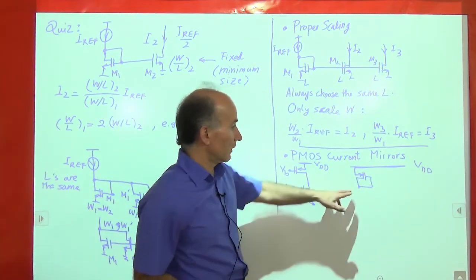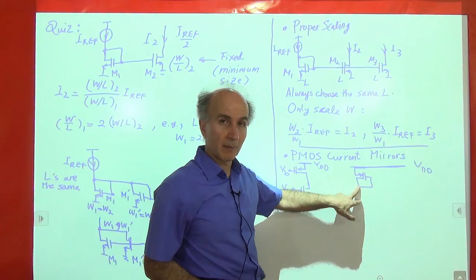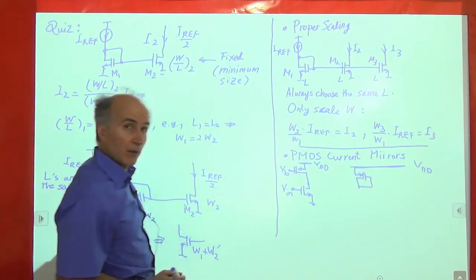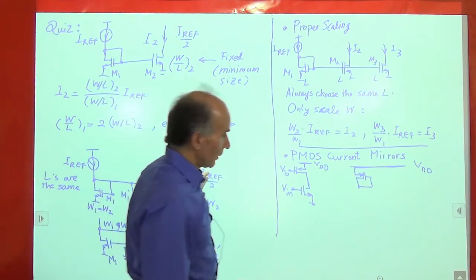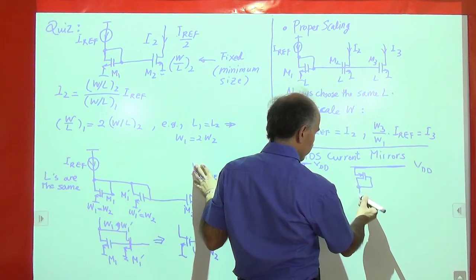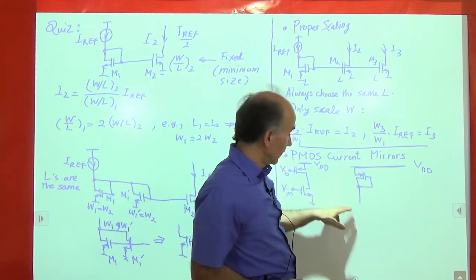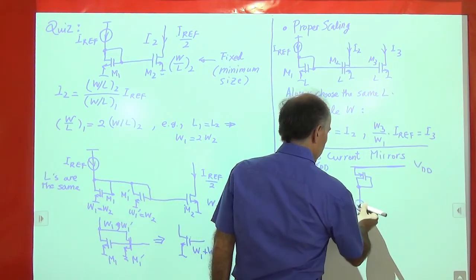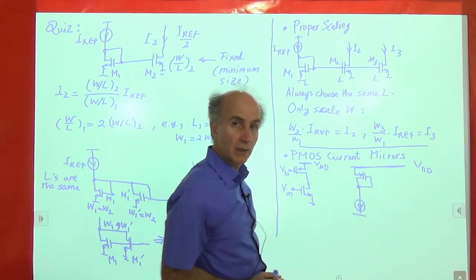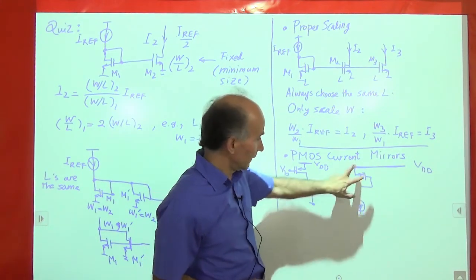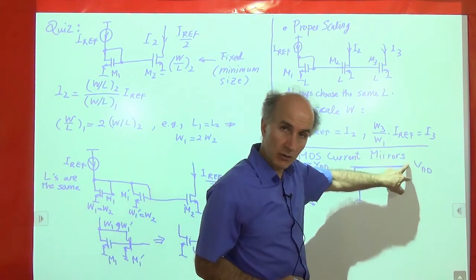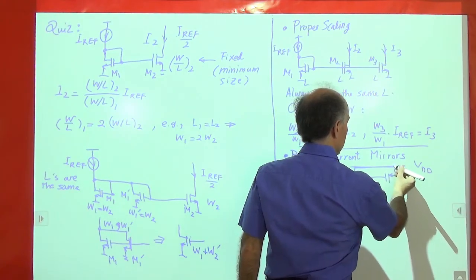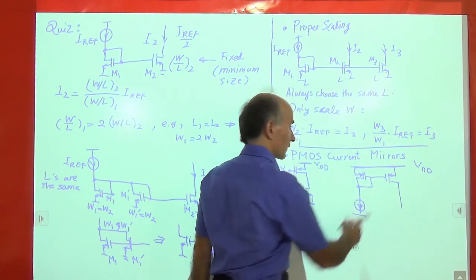Now we need to inject a current to this device so that it creates the right amount of VGS. We did this here, right? We injected this current to create the right amount of VGS and all over the place. Okay, so I need to inject a current. And this current is going from this node to ground. So here's a current that we draw from this device to generate the right amount of VGS. Now we take this VGS and give it to our destination transistor, like this guy. So that goes here, and that will be the current source that we want.